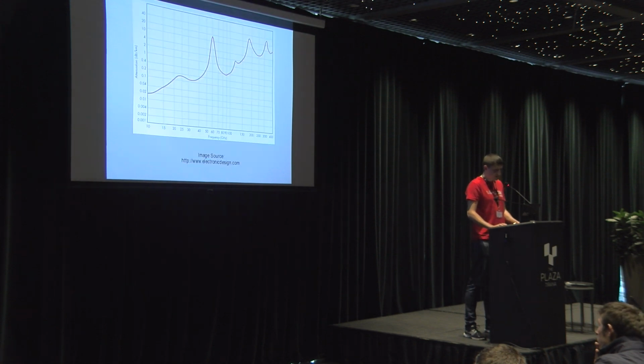Here we can see that historically the 60 GHz frequency range wasn't used in radio communication because it has relatively high dB per kilometer absorption by oxygen. It means the main disadvantage is it gets pretty well absorbed by oxygen, and it is also a plus because it doesn't create as much interference as it goes for 2.4 and 5 GHz radios.